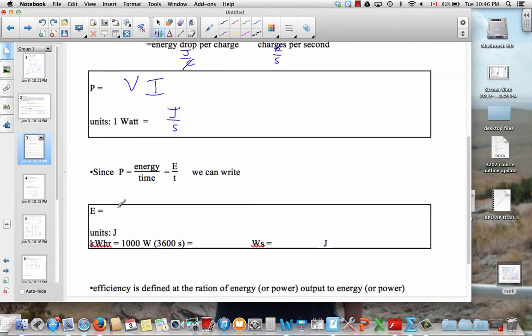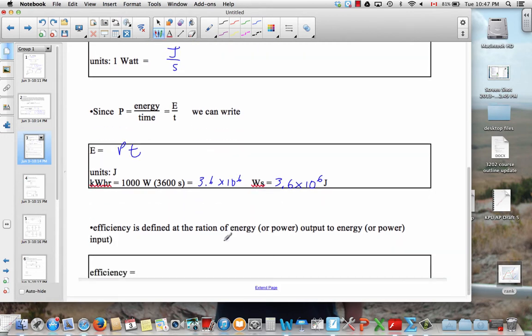Now, if you need to solve for energy, you just multiply the electrical power by time. That would, of course, be in joules, but a joule is a fairly small amount of electrical energy, so it's conventional to use something known as kilowatt hour. Kilowatts 1,000 watts, an hour is 3,600 seconds. Multiplying those together, you get 3.6 million watts times seconds. But watts times seconds is, of course, joules. So a kilowatt hour is 3.6 million joules. It's a much larger unit of energy. Your home probably uses 1,000 or 2,000 kilowatt hours each month.